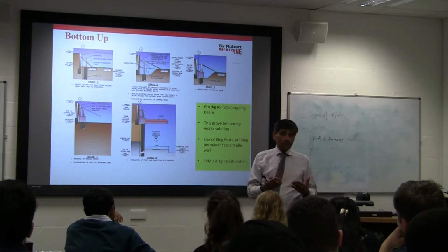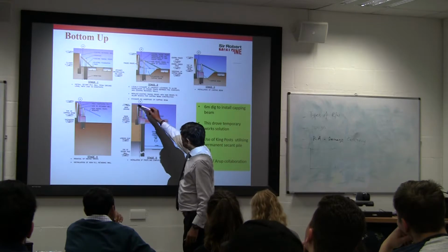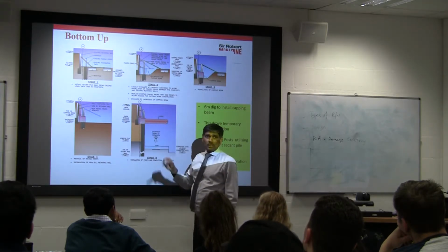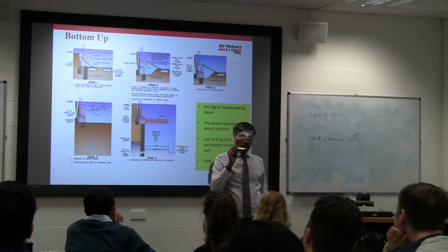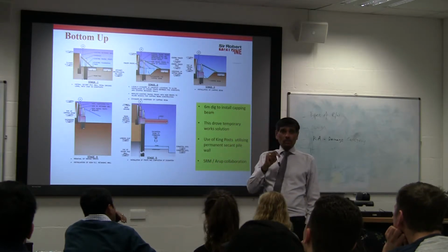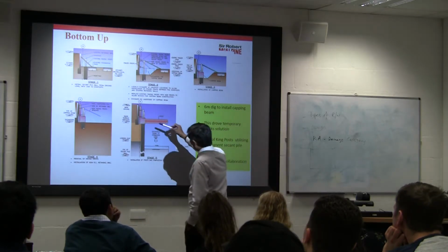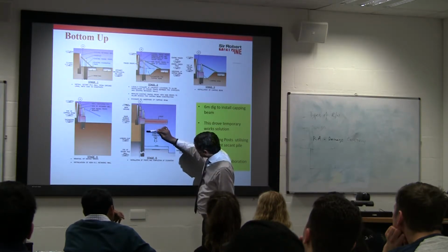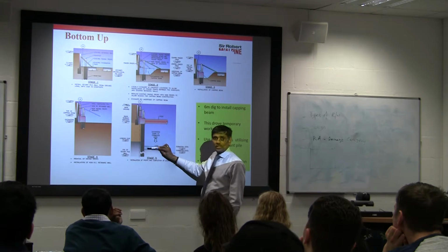the load. We don't want any undue movement here, because that existing party wall, he will be watching, or she will be watching what is happening to that party wall. Those people will be looking at how much the wall is moving before you install. So you install, you lock it here, then you start digging sequentially to the formation level, which is that.